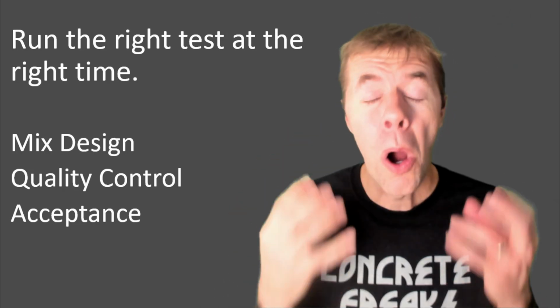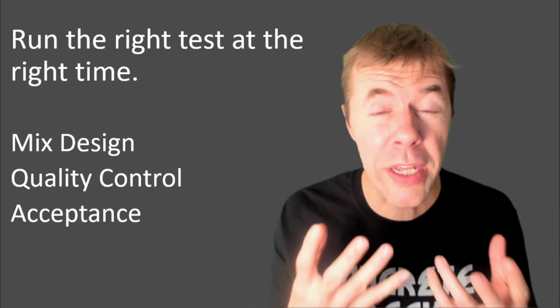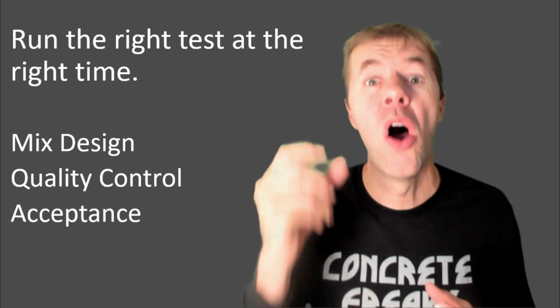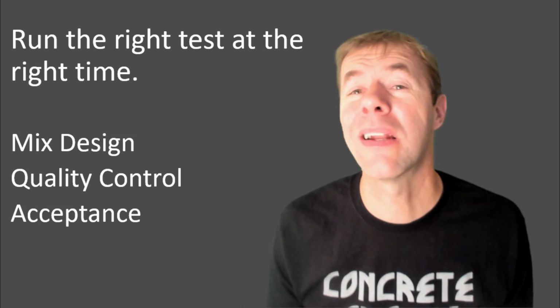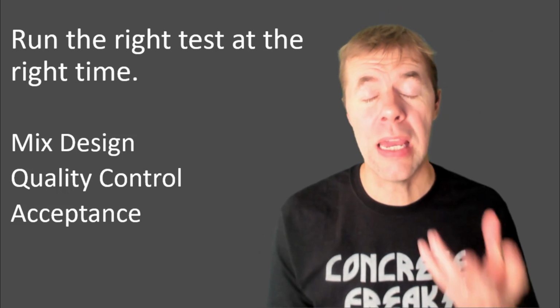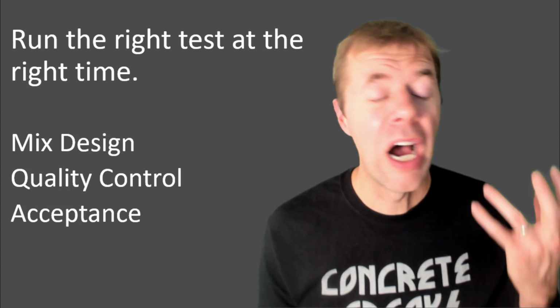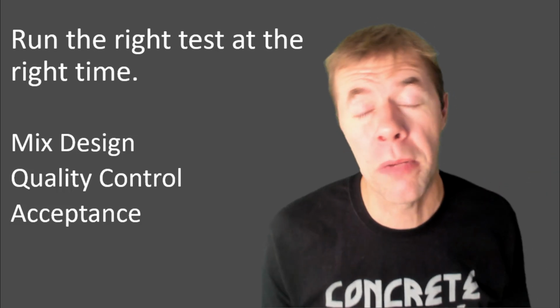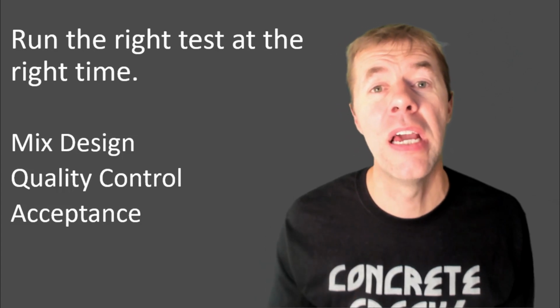Some tests are best done during mix design. Some are best done during quality control. As they're making the concrete, are we making sure they run it right? And then some are best done at acceptance. That's when we say, yep, this is good stuff. I've tested it. I've validated it. That's usually done by an owner or a third-party rep to make sure that this testing is done right.